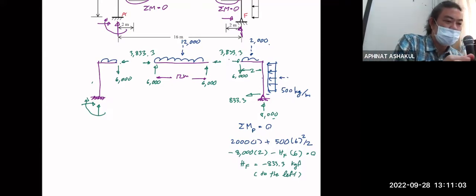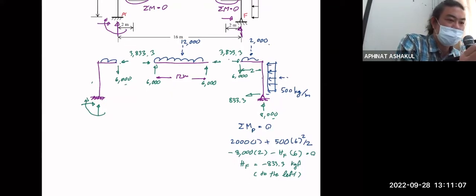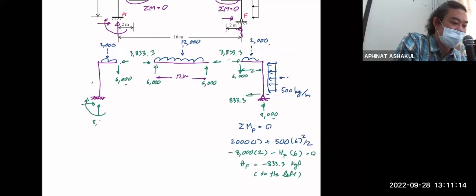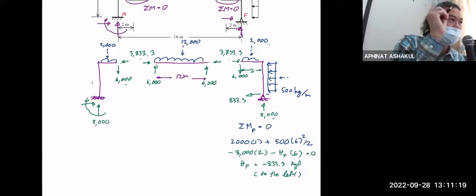So now you know you can start filling in 6,000 here again. And now you know the total force is just like on the left side, that's 2,000. So now you know the vertical reaction here is 8,000. And now you got this one solved. You see, if you don't take the moment on the right piece here, you will not know the horizontal forces. And now you realize that this reaction is somewhat greater than the vertical reactions themselves. That's the nature of the force.